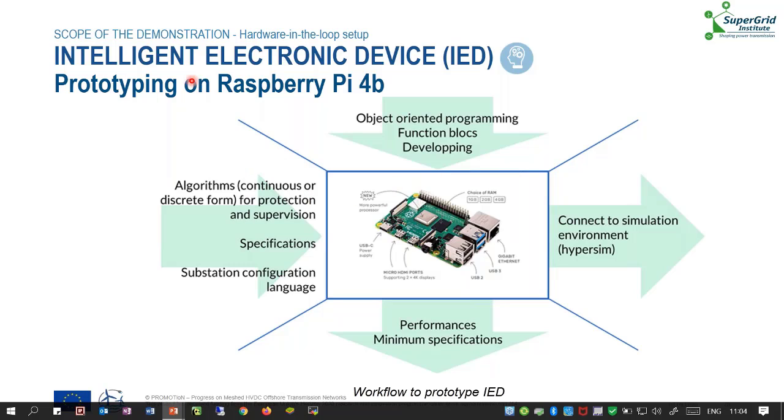It defines, for example, the algorithm requirements and its performance. The coding aspect focuses on the methodology to implement the specified algorithm into the IED, so it will be a code structure. And the communication creation concerns here the learning and use of the IEC 61850 library.